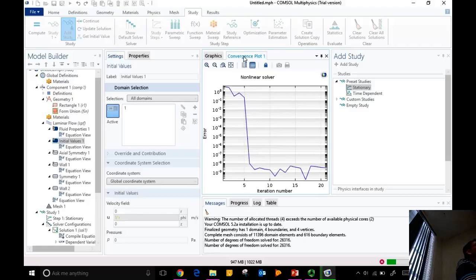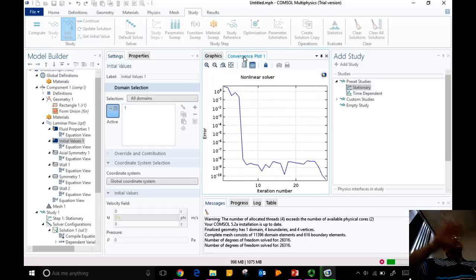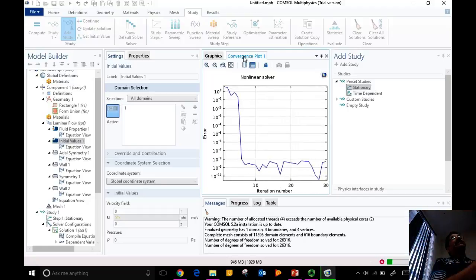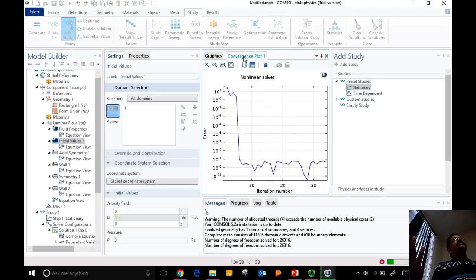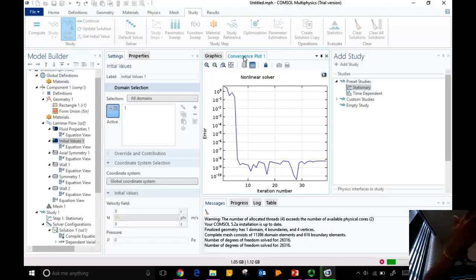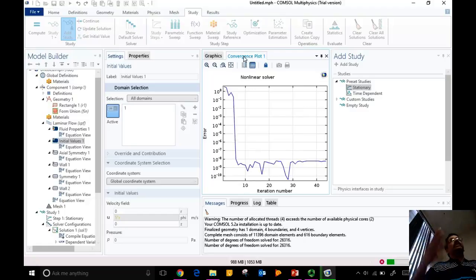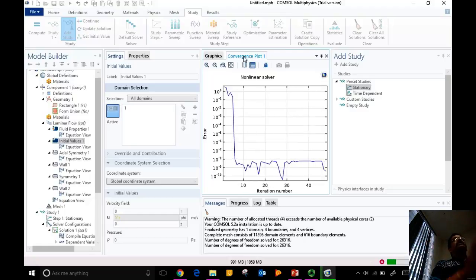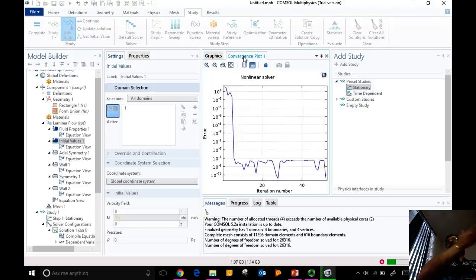In fact, that's one way of getting to steady state: to pose the problem as a transient problem. Then the meaning of the initial condition is that it is truly at time t equal to 0, velocity everywhere is 0, which is a feasible operating condition. And then you rotate the thing and it will control the step size to control the error. Right now it's just making a guess and solving a set of algebraic equations to satisfy the differential equation. In the transient case, it will solve a set of ordinary differential equations matching the error at every time step.